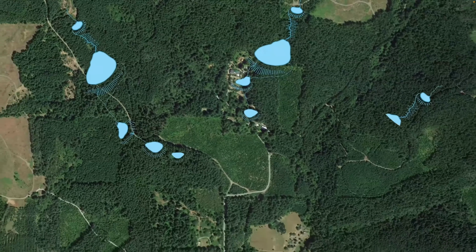The trickle tube usually just has a single cutoff collar. You can have more than that, but the trickle tube also needs to be outfitted with a cutoff collar. Another option for the outlet pipe is to have the pipe just go right over the top of the dam and have a siphon. That's a sort of easier and safer way to go, but it takes a little bit more maintenance.